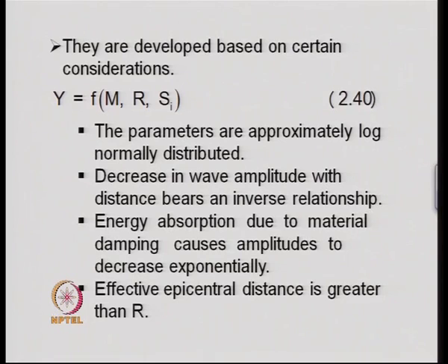Secondly, in obtaining the attenuation law, it was observed that the decrease in wave amplitude with distance bears an inverse relationship. Then the energy absorption due to material damping causes amplitudes to decrease exponentially, and this was also seen from previous earthquake data.